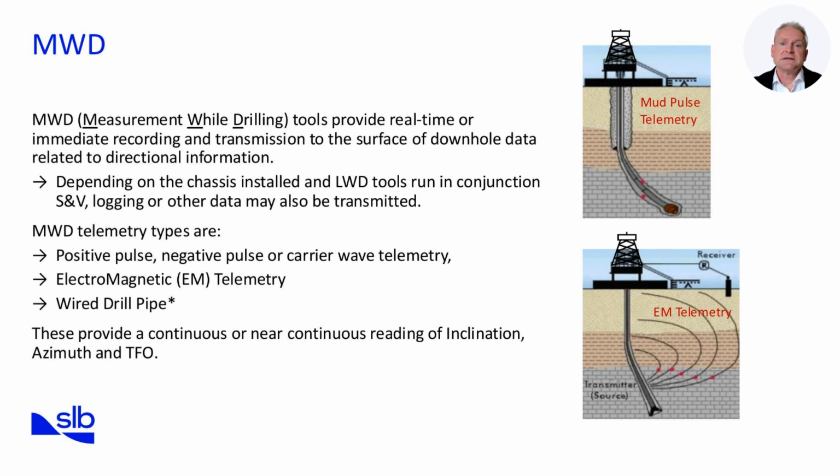As the name suggests, it refers to the process of gathering measurements, particularly directional and environmental data, while the drilling operation is ongoing. The data is transmitted to surface in real time. There are 3 different systems which can be used. First, mud pulse telemetry. This is the most widely used form of telemetry, especially in deep or offshore wells.